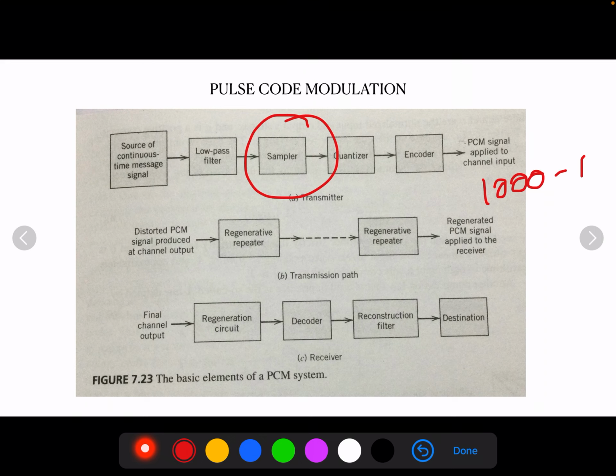By using a non-uniform quantizer with the feature that the step size increases as the separation from the origin of the input-output amplitude characteristic is increased, the large end step of the quantizer can take care of the possible excursion of the voice signal into the large amplitude ranges that occur relatively infrequently.